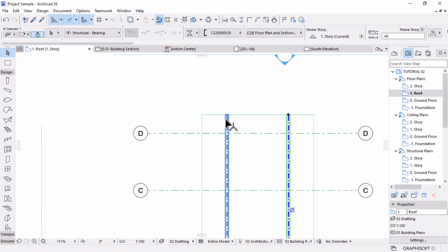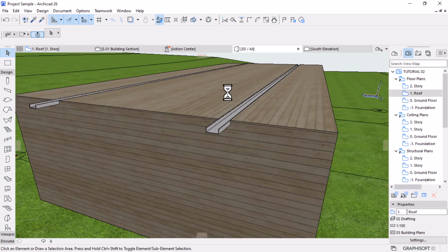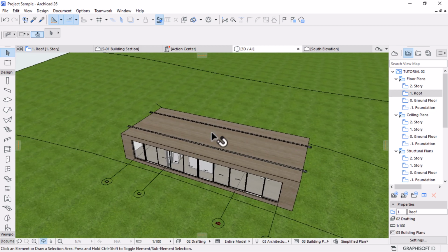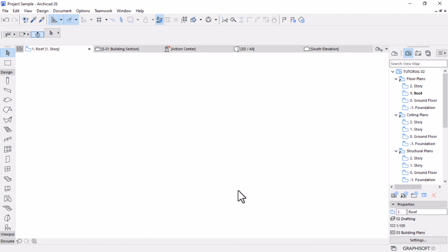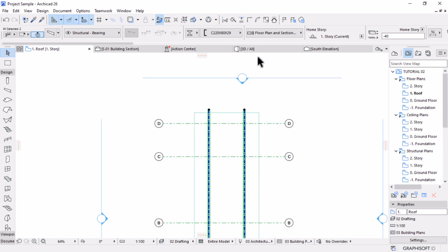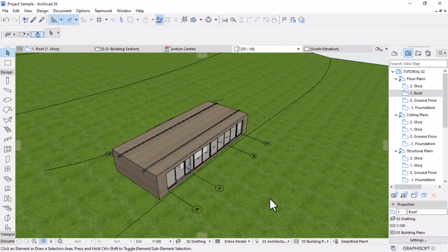So what I want to do is to stretch this to this point, or you can use the adjust, and then you can adjust them to this area. Do the same to the side, adjust them to this point, so that when water comes, it goes straight off. It looks huge. Okay, this side is better, that side is huge. So we can reduce this. Let's use the same adjust tool and trim off that. Okay, yeah, it looks much better. It looks much better that way.